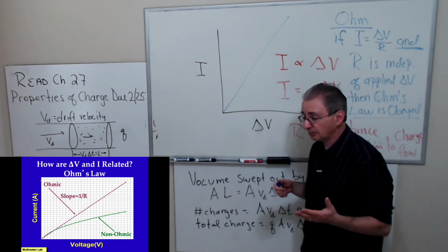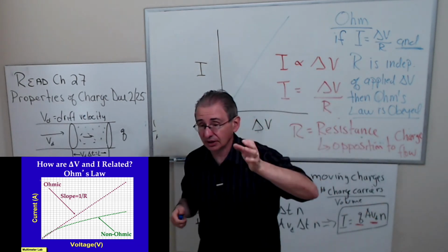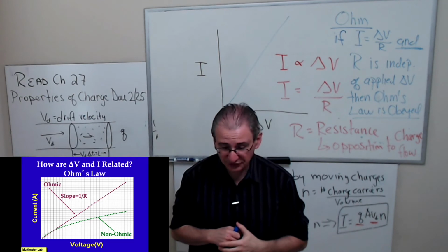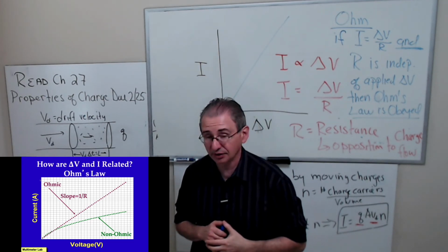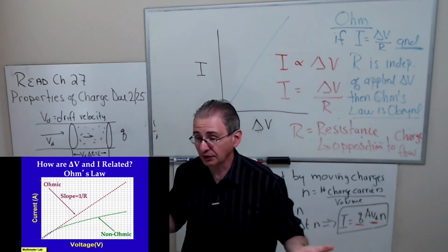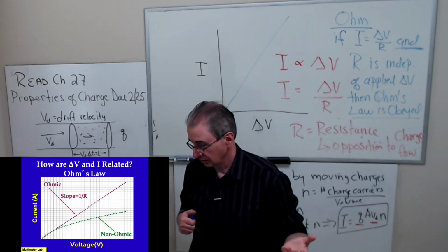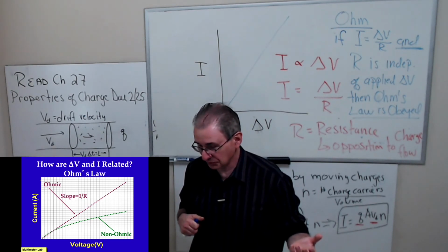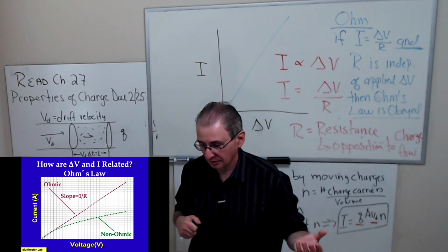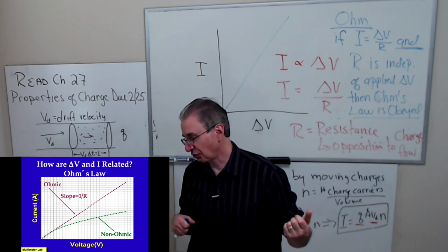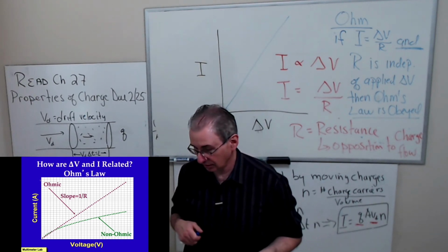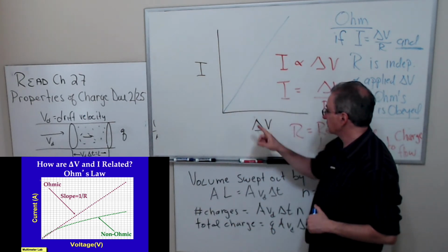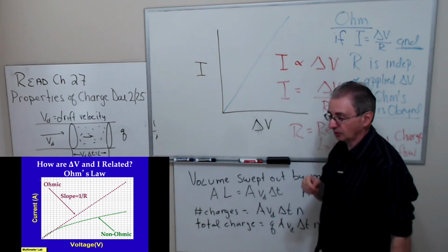Do all materials obey that principle? No. I mean, you guys have studied Hooke's law. What's Hooke's law? Well, that represents the relationship between the force on the spring and how much you stretch it. What if you take a spring and you stretch it too much? What happens? You destroyed it, right? It's not going to be elastic anymore. Well, same thing with Ohm's law. There's a limitation to this. If you put too much of a voltage on the material, this won't be a straight line anymore.